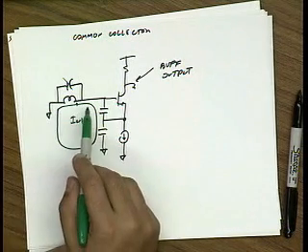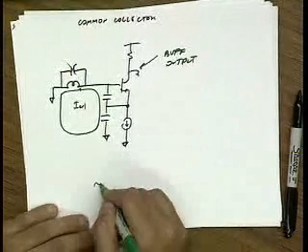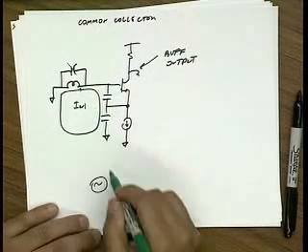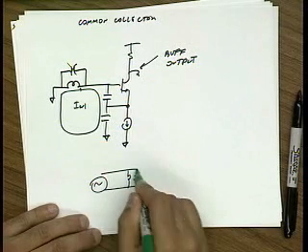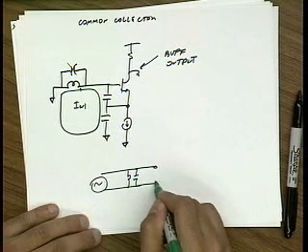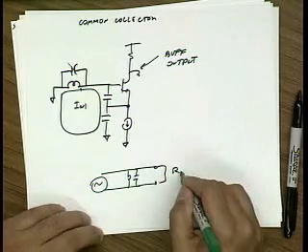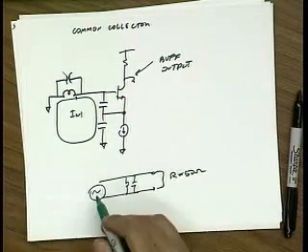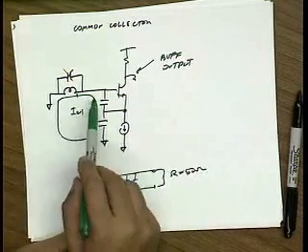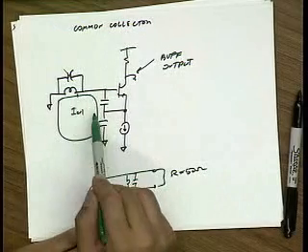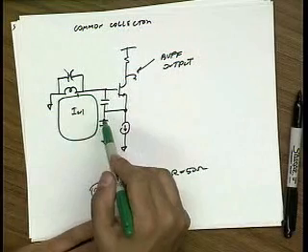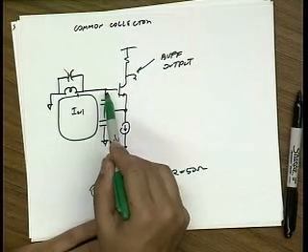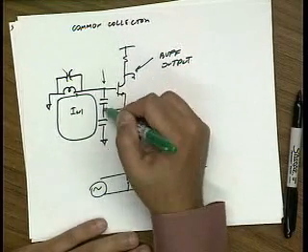So remember, you always need a buffer. If I have an oscillator, let me represent it as an LC tank, I can't just stick a resistor here, let's say 50 ohms, because that'll de-Q the tank. If this is driving a transmission line, I can't put the transmission line lead here because that would stick 50 ohms